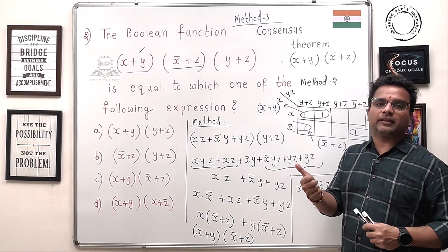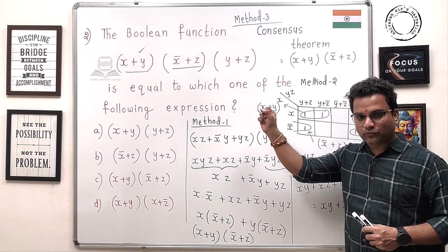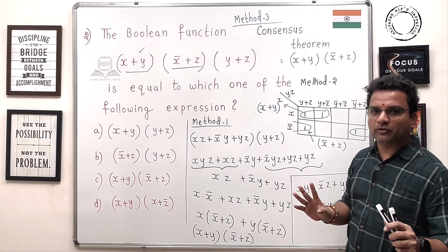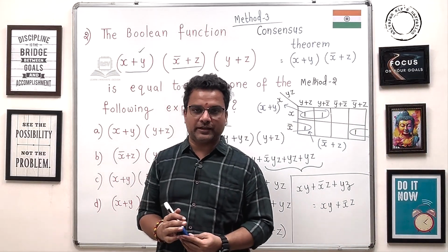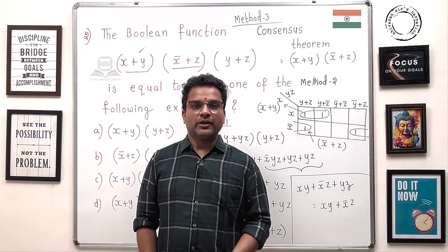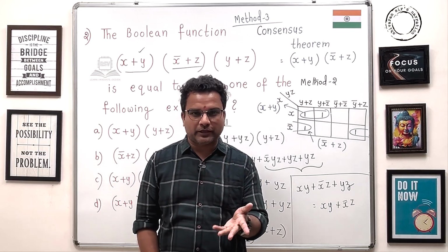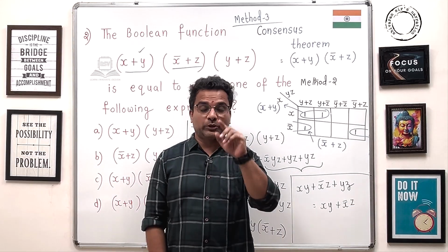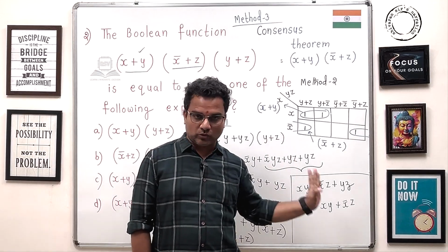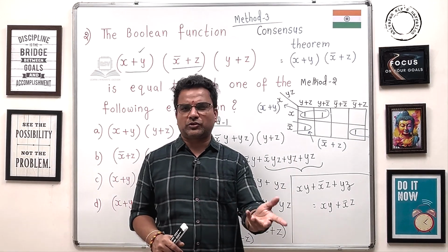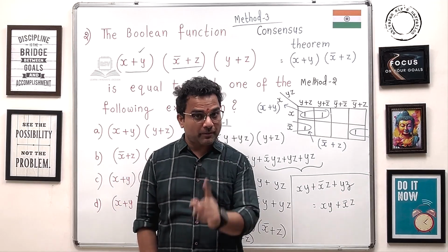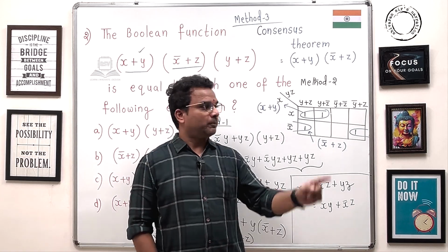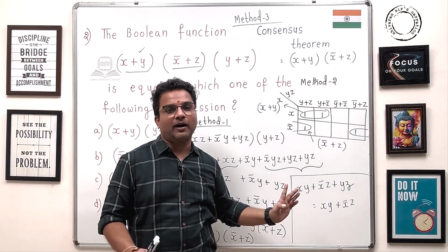You can easily tell the answer: whichever has the true complement form and the true form, you take those terms. That's it. That will be your answer. This is the simplification, guys. And the takeaway from this video is, if the number of variables is more than 3 or equal to 3, it's better to use K-map unless otherwise mentioned. Moreover, you need to remember the consensus theorem also. It is not only De Morgan's law, involution law, idempotent law. No, you need to remember the consensus theorem also. And the consensus theorem is applicable to POS and SOP also.